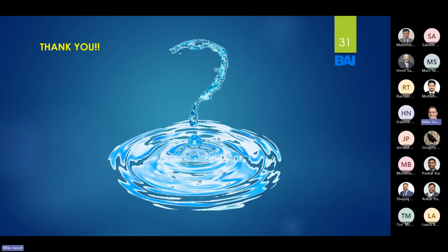There are things that they can put in place that will measure how much silt has washed away, even if new silt is put back in place. Probably the simplest way to think about it is like a donut on a pile, and this donut rests on the stream bottom. When the soil underneath washes away, that donut drops, and there's a gauge that measures how far it drops. So even if the silt comes back over top of it later on, you know how much silt has scoured away.